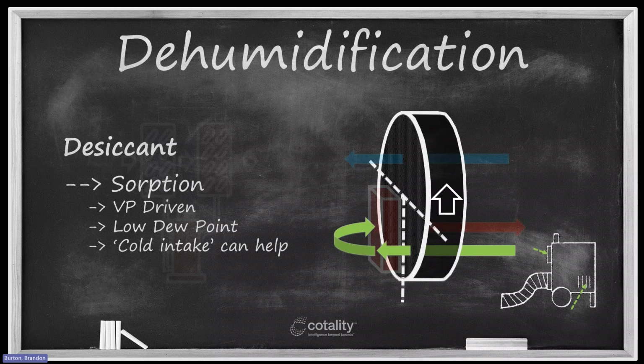So this is another area where desiccants can really excel, if you have the means to provide preconditioned, cooled air to the intake of a desiccant dehumidifier, you're going to notice a significant boost in their performance. Whether that's because there's an existing air conditioning system operating within the structure, or there is cooler air available outside the structure, in either case the desiccant dehumidifier can see a significant boost in performance if you pre-cool that incoming air. So that is the desiccant dehumidifier versus the refrigerant.